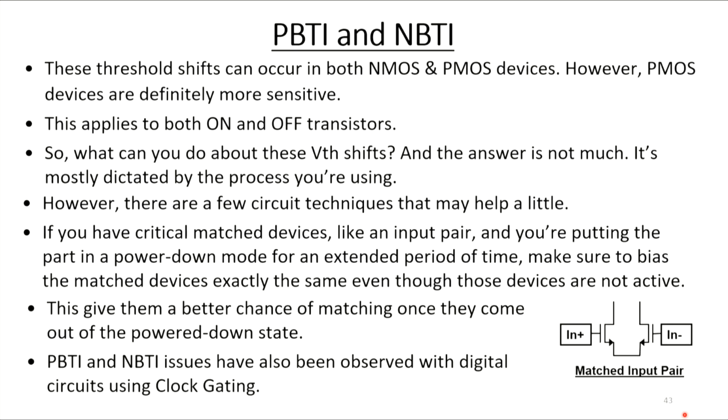So these threshold shifts occur in both NMOS devices and PMOS devices. However, PMOS devices are definitely more sensitive, and this applies to both on and off transistors. So what can you do about these threshold shifts? And unfortunately, the answer is not much. It's mostly dictated by the process you're using. However, there are a few circuit techniques that may help a little.